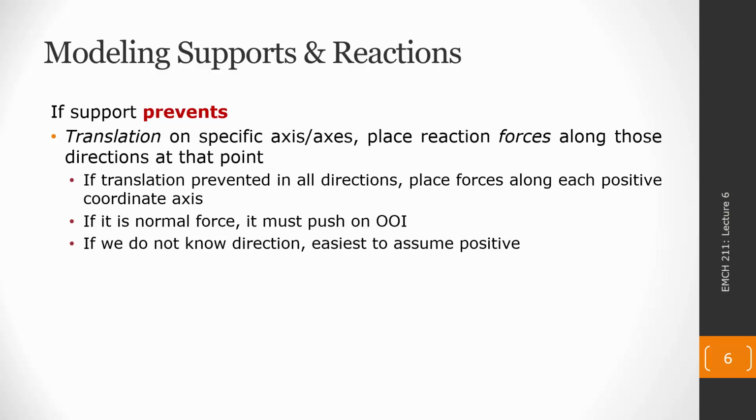And we're going to see here, if we don't know the particular direction of a force, but we do know along what axis it is acting, we can just, for the sake of easiness in the math, assume that it's going to be acting in the positive direction. And then we're going to let the final mathematical results tell us, was our assumption correct or incorrect? Was it actually facing the opposite direction? The assumption of the positive direction is really just done for consistency and simplicity, and we're not necessarily thinking that forces are going to be acting along that positive direction, but we're going to let the negative or positive sign at the end tell us.